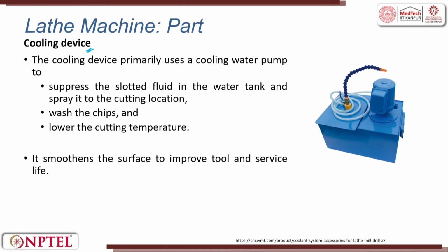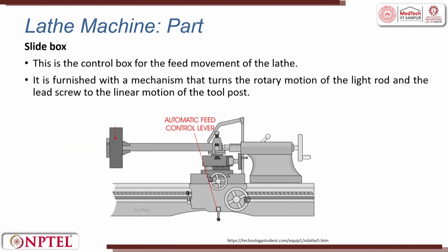It supplies cutting fluid at the location. This cutting fluid is used for washing the chips, lowering the temperature, and also for lubrication to reduce the friction between the tool and the workpiece. It smoothens the surface and improves the tool life and service condition.